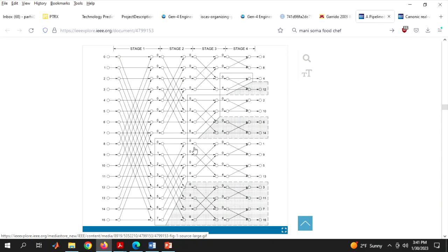And that half complex, if you expand, becomes one full real. So in a way, what we have accomplished is we still maintain the n by 2 butterflies in each stage, but in each and every stage, we have n by 2 real butterflies and not n by 2 complex butterflies.